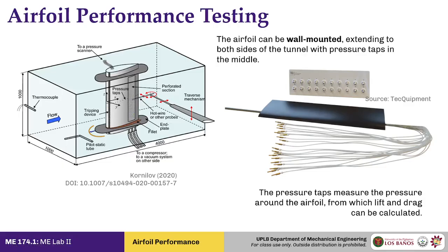And this is, in fact, how a lot of the old airfoil data has been calculated. So you typically see tables upon tables of pressure distribution data. Sometimes they don't generate the lift and drag tables anymore. They just go right ahead and maintain the pressure distribution. And it is true that from there you can generate those data, the lift, drag, whatever it is that you want to generate.